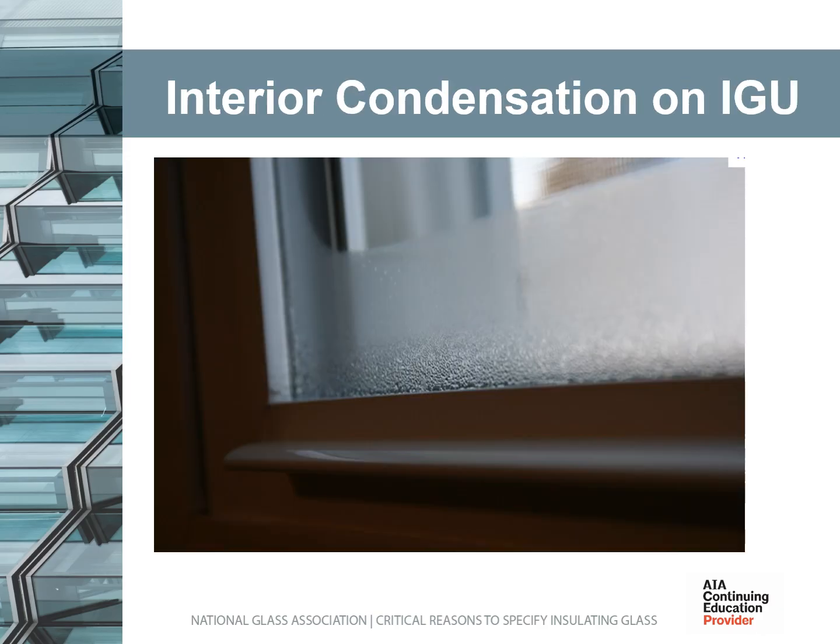Here's an example of a unit with considerable condensation. In some cases, the impact of such condensation can be so severe that frost and/or ice can form on the interior surfaces of the window. This can lead to a variety of problems, including water damage and poor indoor air quality. Efforts to improve fenestration system performance to improve condensation resistance include optimization of framing materials and thermal breaks, control of air leakage through weather seals and frame joints, and the optimization of the insulating glass unit component.